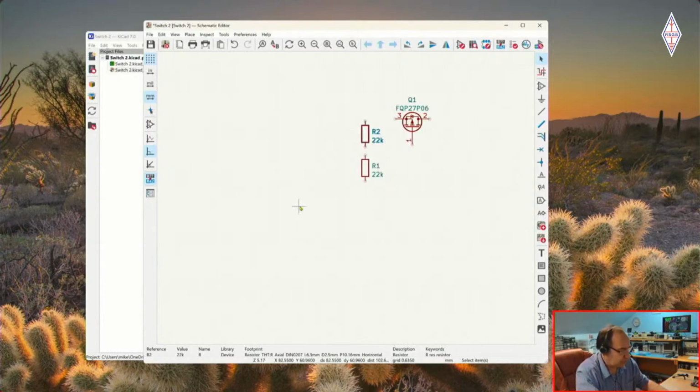And actually, I'm going to duplicate it again, so this time with Control D. So at the moment it's just duplicating the footprint that you decided, because presumably all your resistors are going to be the same size, so this will work for all of them, yeah? That's right, and I'm going to rotate that one because I know that one needs to go over there in my schematic. And I'm going to grab this one again, and I'm going to duplicate it again. So that's now all the resistors put in without too much effort.